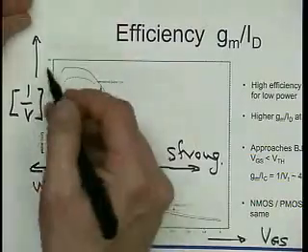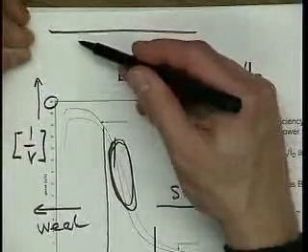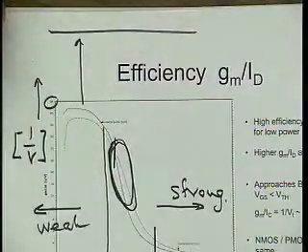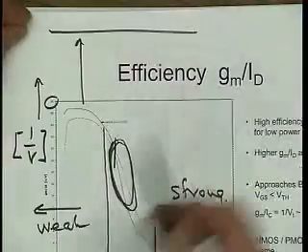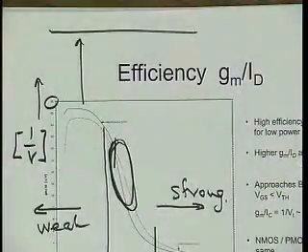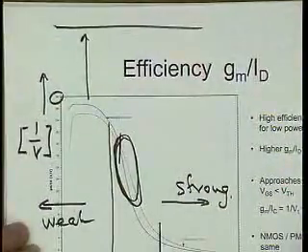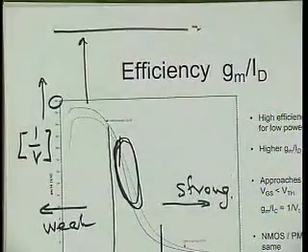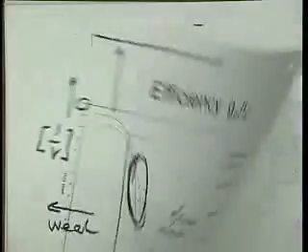So for a bipolar, this number is actually 28. So a bipolar would be up here, which would be about 50% larger, because n is 1.5, than the MOSFET. So for a BJT, there is no VGS, there is a VBE. A BJT is always up here in efficiency. Okay, that's why we like these BJTs, right? Unfortunately, they have a few other characteristics that we don't like so much, so we don't use them nearly as much anymore. But that's what's going on.